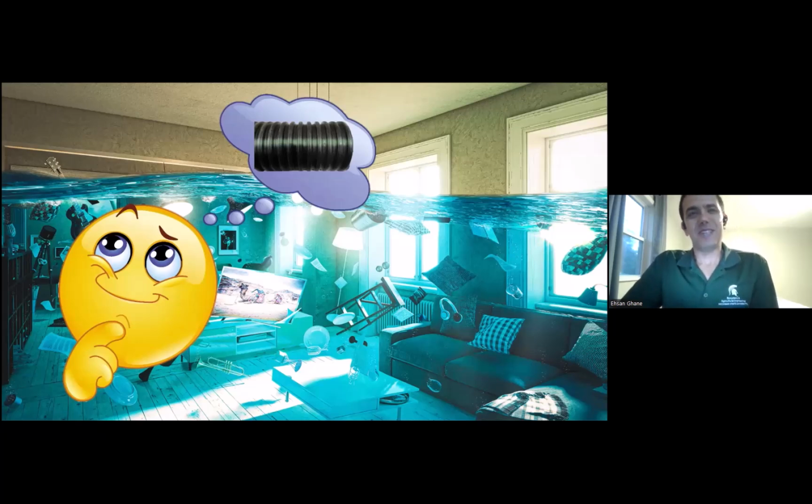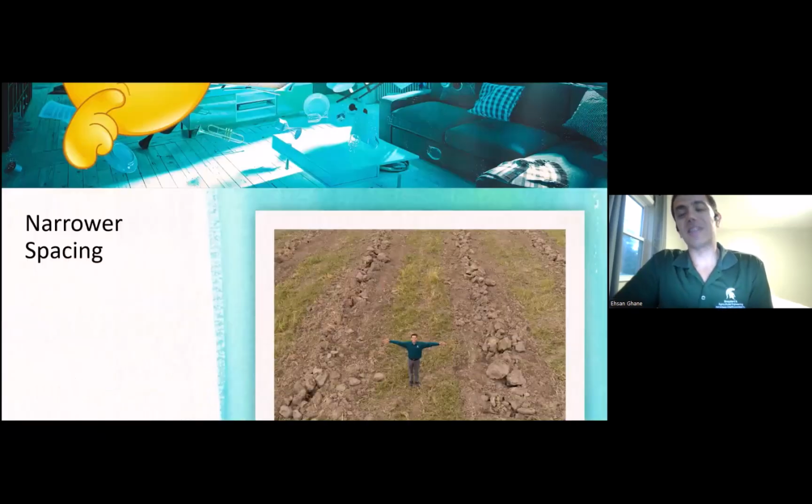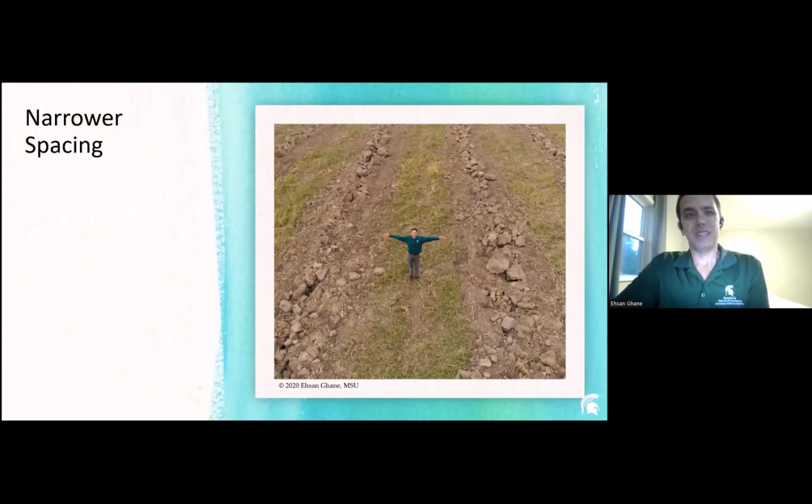In some cases, as I mentioned, the field is undrained and you put the tile in, or you already have drainage and you want to go narrow spacing. This is another thing that comes to our mind too: you already have a drainage tile system, and you're thinking that I may need to go narrower now, or we call this splitting the lateral spacing. So all of that climate disruption, all of that extra water, could be a trigger for thinking about this narrow spacing.